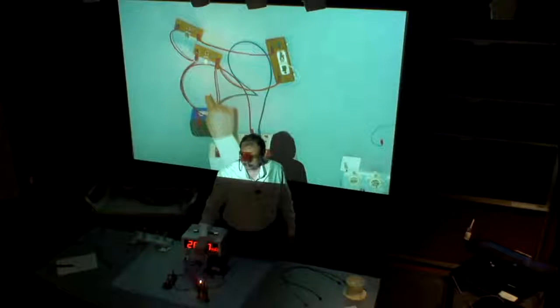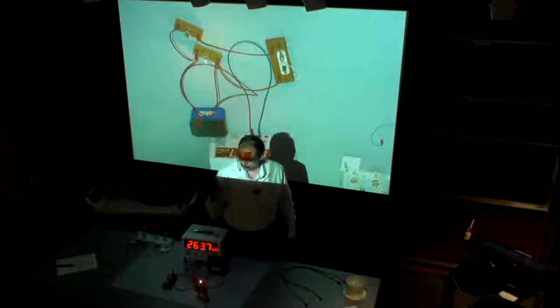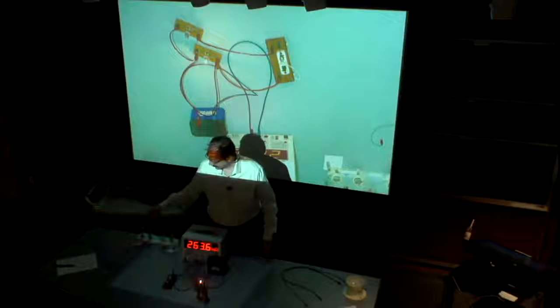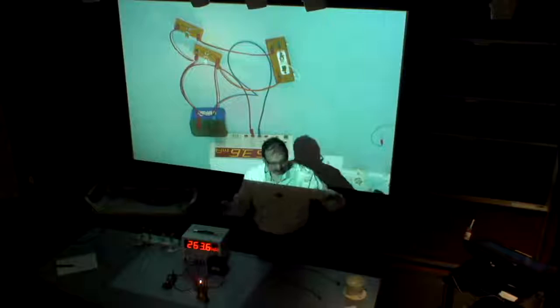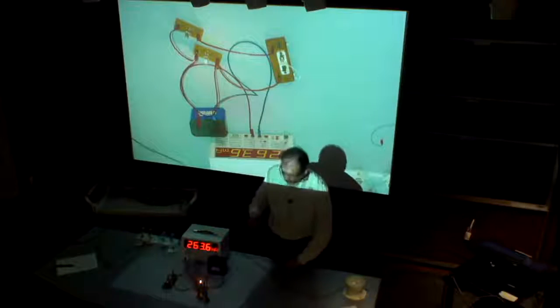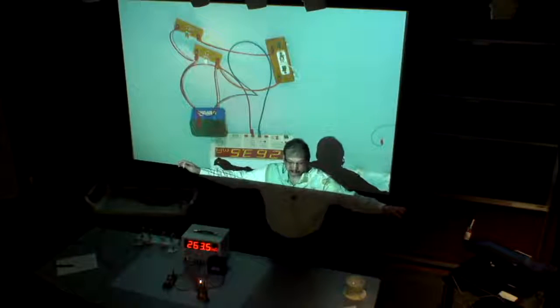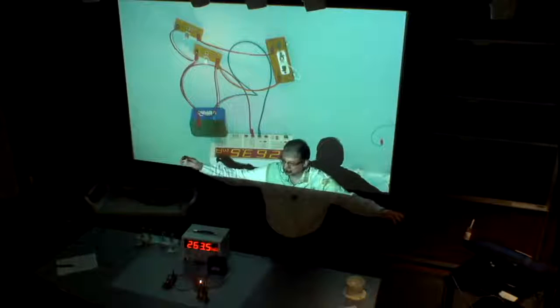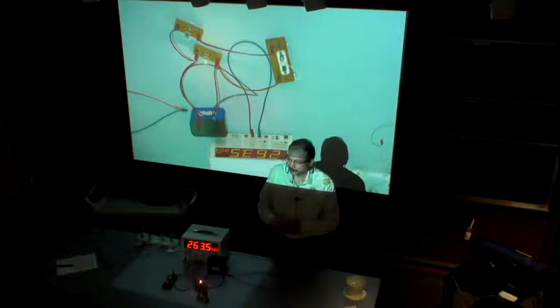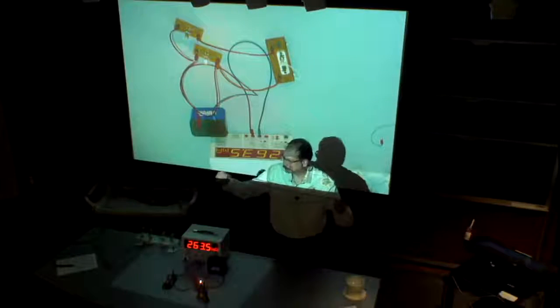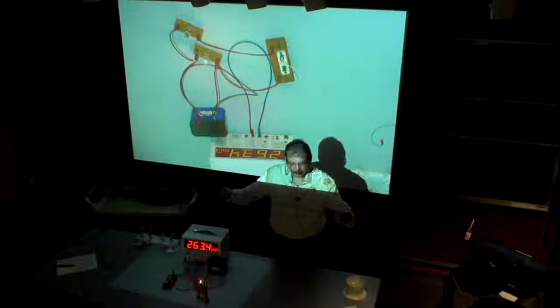It's all about the way we wire them up. We have two options, in series or in parallel. If we're adding elements in series, it's like having one wire and then adding an extra after, so we're increasing the length. And when we're increasing the length, how does it affect the resistance? Increases, the resistance should go up. But if we have elements connected in parallel, we don't increase the length, we increase the area. So how does it affect the resistance? Decreases. The resistance should go down.